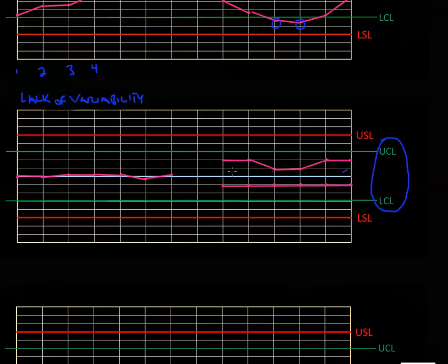Sometimes you see gauges, maybe the chart was set up for, we'll say, calipers with 2 places of resolution, and for some reason this person's only using calipers with 1 place of resolution. So some of the precision gets boxed out.